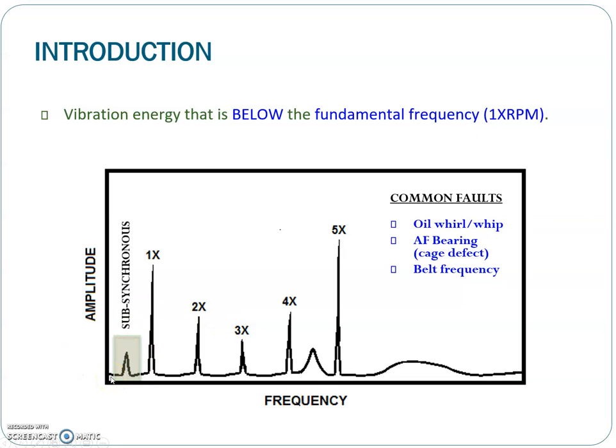The most common faults that are associated with subsynchronous vibration are oil whirl, oil whip, rotor rubbing, cage defect at the anti-friction bearing, and belt frequency related faults.